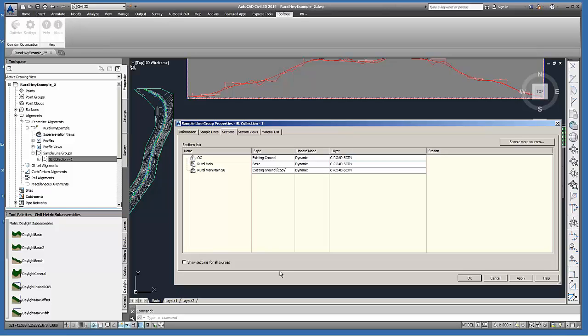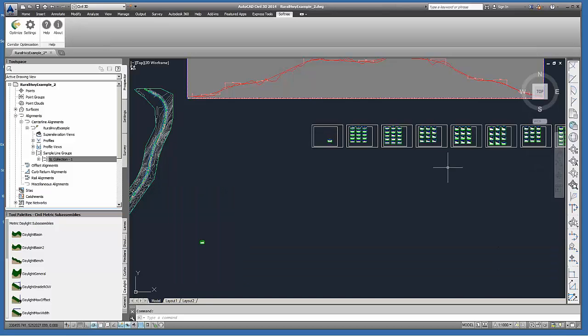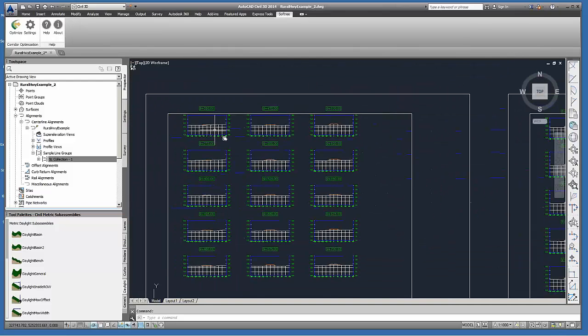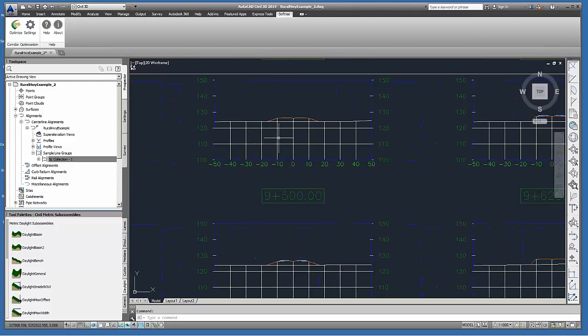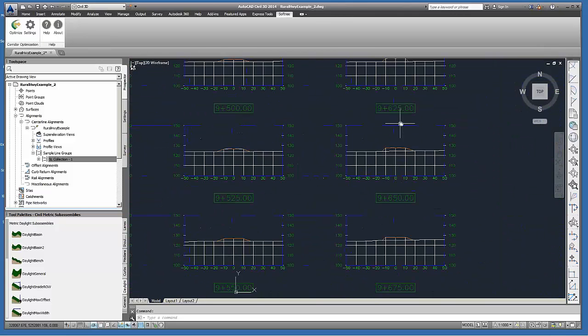So when the corridor is rebuilt, the corridor surface is built, and this is your standard corridor surface. And because we're doing optimization, I've only included just the subgrade surface, and that is all pretty standard Civil 3D stuff. So I've taken those items and placed them on cross sections, on sample lines, and you can just see here some of the sample lines.